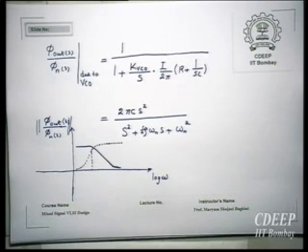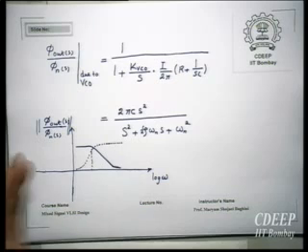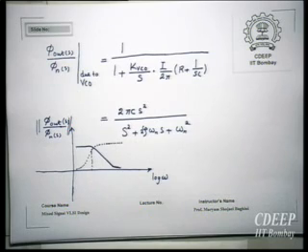So what does it mean? If we want to get rid of this problem, we have to shift the cutoff frequency of the filter to the right. Essentially the closed loop performance of the PLL should be such that the cutoff frequency increases, so that we can attenuate the jitter of the VCO.